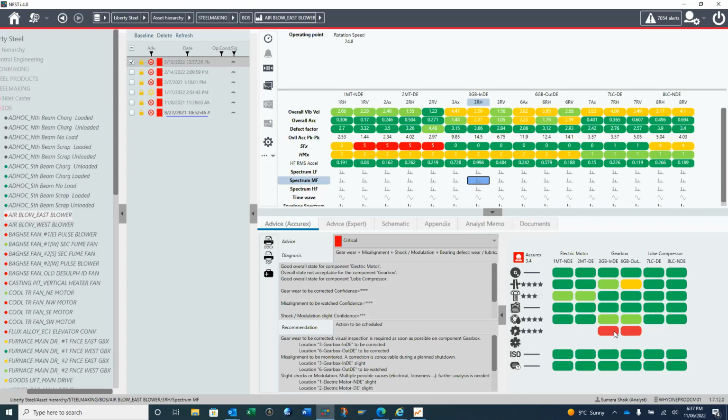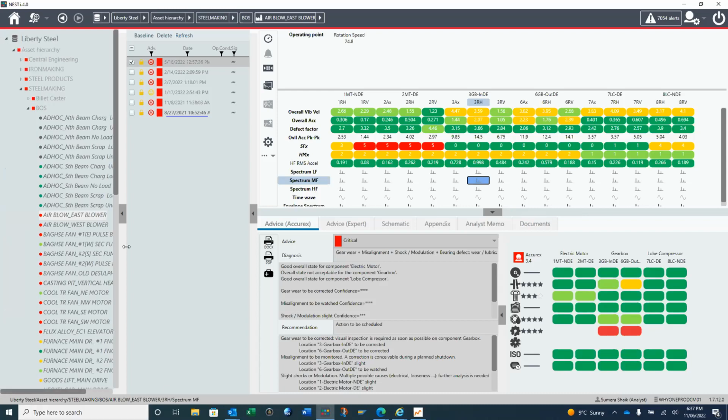You know my trend in my seawater cooling tower, how many years? From 2012, 13, 14, right? In 2014, it went to 20 mm per second, right? So your gearbox is only 2 mm, 3 mm per second. Very safe.